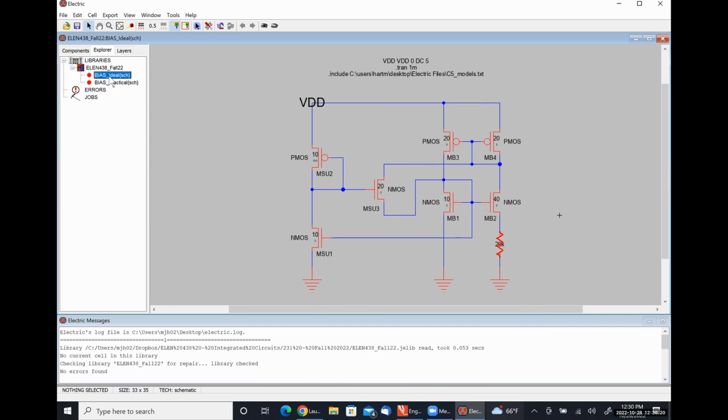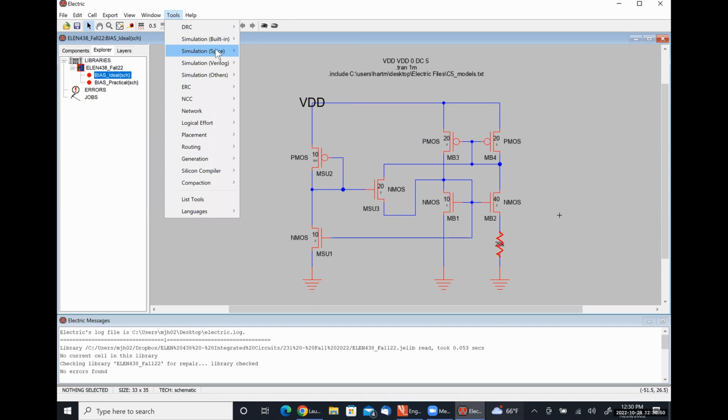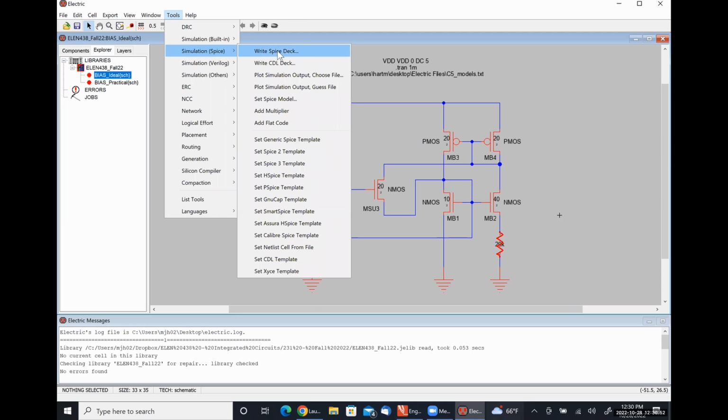What we are going to be doing today is pivoting to drawing this in a schematic view, because I didn't have a chance to figure out what was wrong with the layout view and why it was behaving poorly or oddly. I don't know if it's behaving poorly or not. I drew this circuit, just the startup circuit and the beta multiplier reference circuit, and I'm going to give you a simulation to show that it's behaving as we would expect.